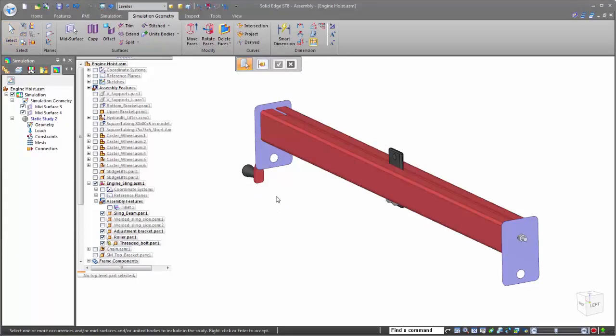The first step in our study setup is to pick all of the geometry that we need. Since the bolt isn't meant to be load-bearing, we'll just leave it as a point of reference. Now that we have our geometry, we need to set up the rest of the study. Keeping consistent, we'll do this by following similar steps as the beam study. The first step is setting up our load. Since the weight will hang off of both sides of the balancer, we will distribute the 20,000 newtons between both of the holes in the surfaces that represent the sheet metal end caps.